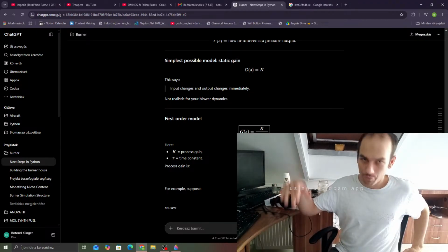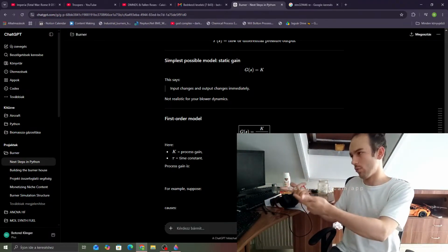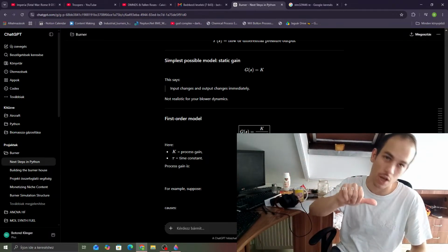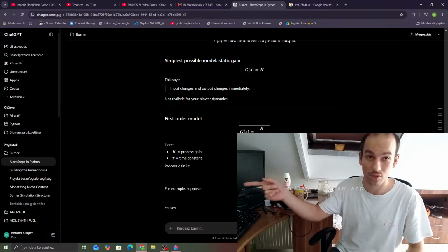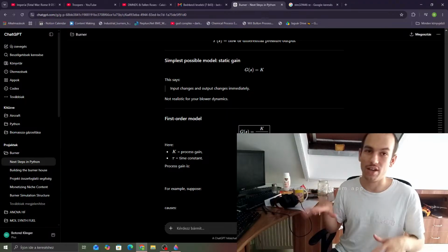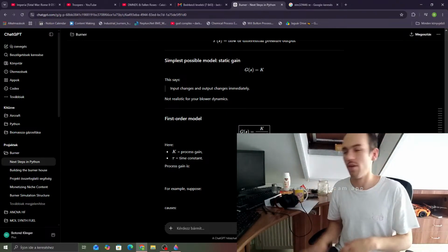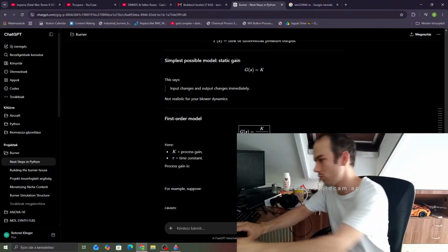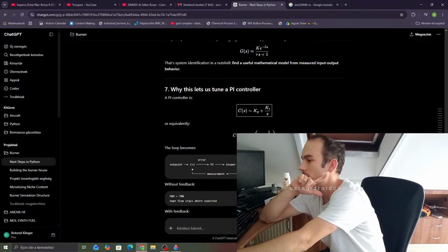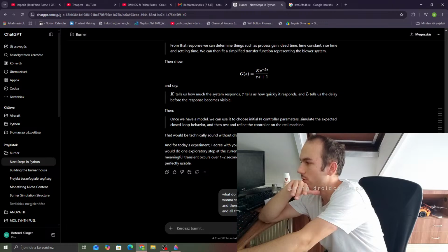And for that we create the controller, but we calculate it from the constants that we derive from either the physical model or from the plots. And that is not done by us because it is kind of hard: you need to tune two things at the same time, so it's an iterative method. There are multiple methods to check, Cohen-Coon is one, Ziegler-Nichols is another. I don't know the other names, but I'll find it.